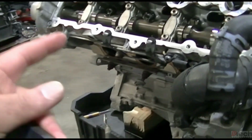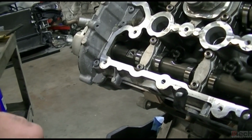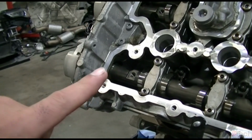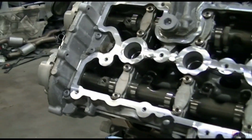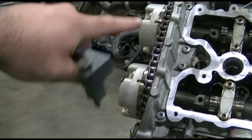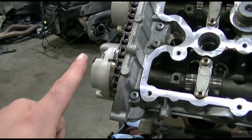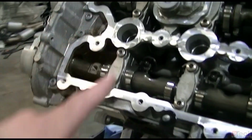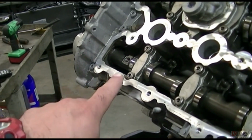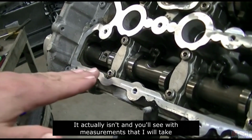So we definitely do have a physical timing, positioning, or alignment issue going on here. Not necessarily a performance type issue due to phasers, unless there's an issue with this phaser, but not 100% sure yet. But it seems like the exhaust cam, more than the intake possibly, it's shifted this way.